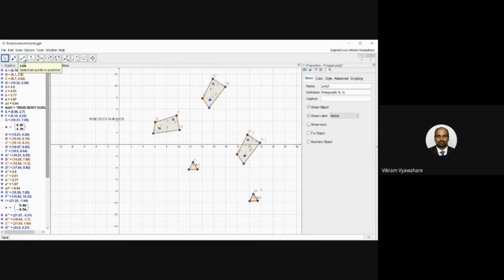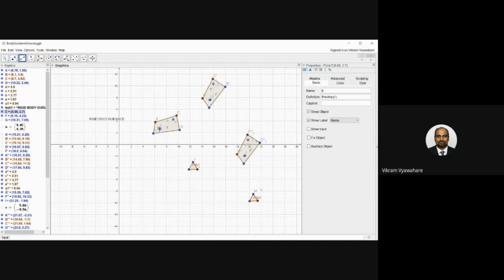But now we will have to follow what is called the inversion method. You choose which link we make fixed, and based on that we get the inversions. So let us see how this inversion method works. Let us say for this pivot location, we will get the distance from each of the points. We can draw these segments.